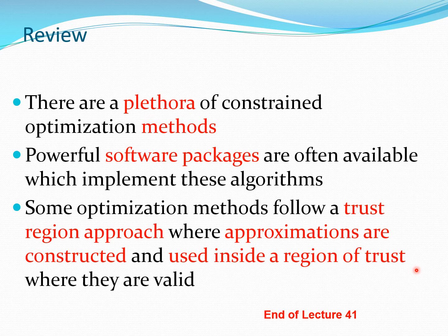And one of the advantages of the response surface method would be that it decouples the analysis problem and the optimization problem. Because as I've mentioned many times, the analysis problem is actually a computer code in most cases, and therefore you do not want to try to link this computer code with large optimization software. Instead, it's much easier to extract functional approximations of this computer code and then to use these separately by using various methods which we have discussed before.